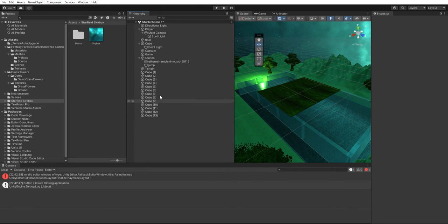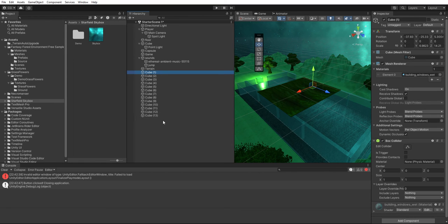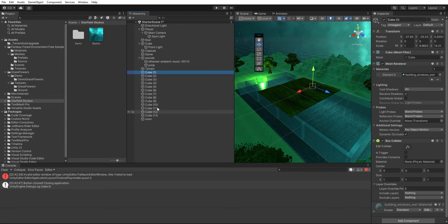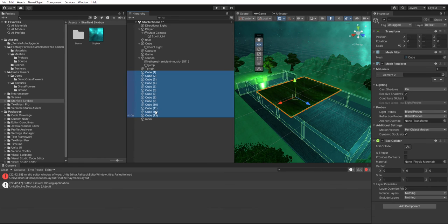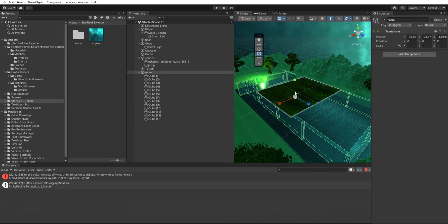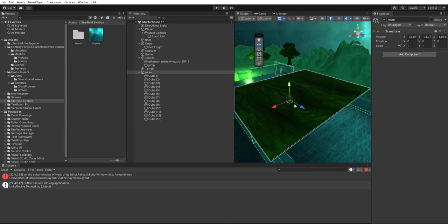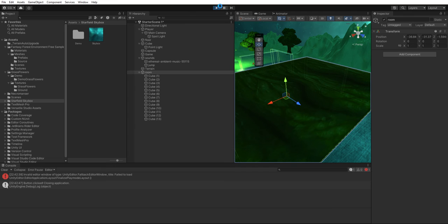Okay, finally, if we wanted to group all those objects together so they're all in one 3D object, that's not empty, sorry, and then room, and then press down Shift, select all of those primitives, and then simply put them under that. Now, if I wanted to, I can just move them all as one. Otherwise I'd have to select each primitive individually, and I can move them around like that, which is quite useful actually. In fact, it's best practice, so it's well worth doing.